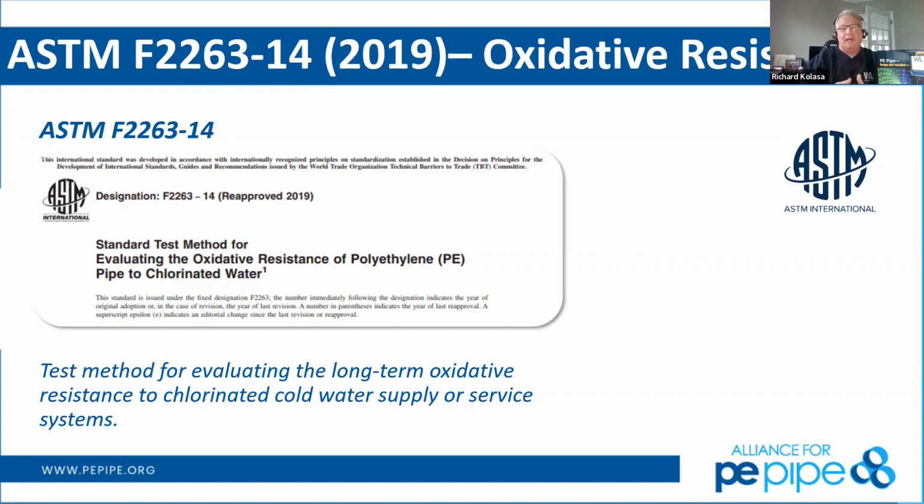This slow crack growth failure mechanism was known and understood by the polyethylene groups, but in Nevada and in these hot arid areas, these tubings got very, very warm, especially on south-facing or west-facing homes, where they came above ground.